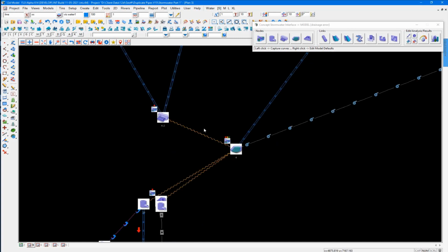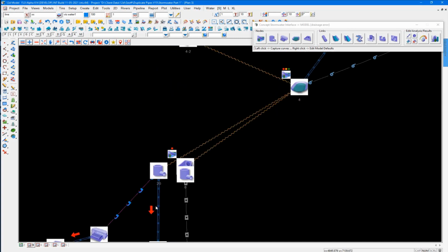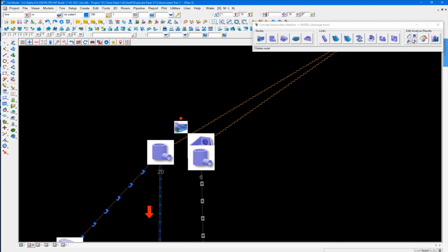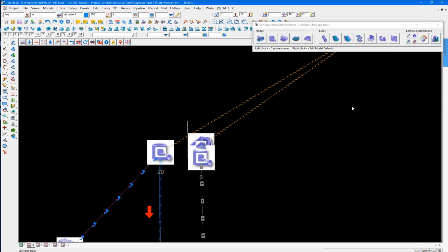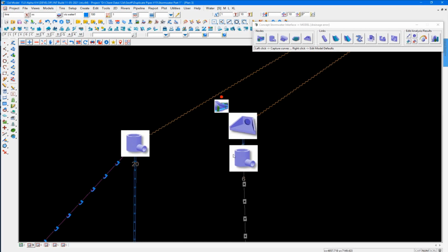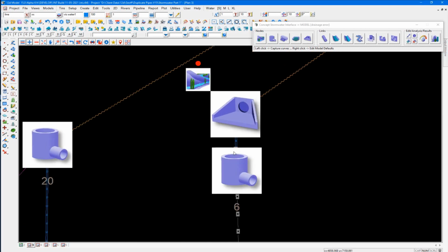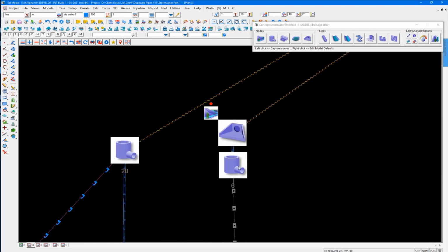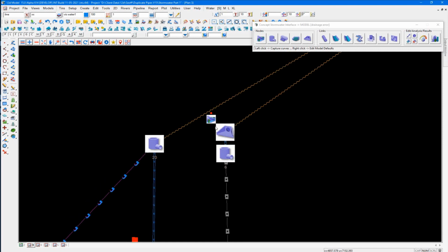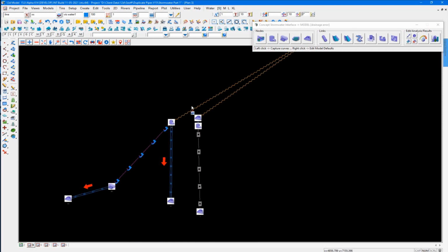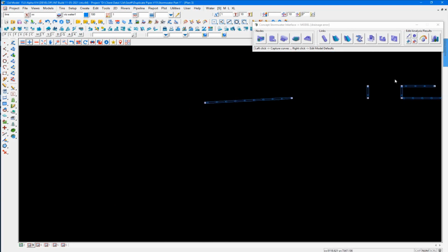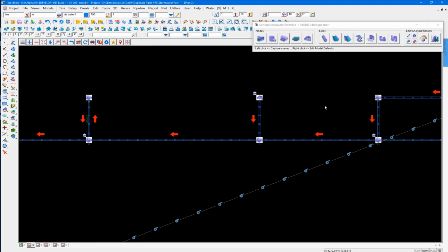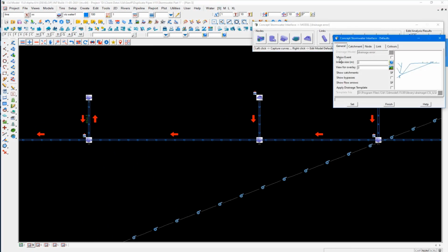Similarly down here we have three basin links, and you can see that we're starting to have a bit of a problem here with how close some of these things are. So I can come back in here and adjust my image size if I want to, just to be able to clean it up a little bit. And there we go. We can see that it looks like a pipe there between the headwall and this node. So this sort of gives us a much neater picture and a much neater way of looking at these things.